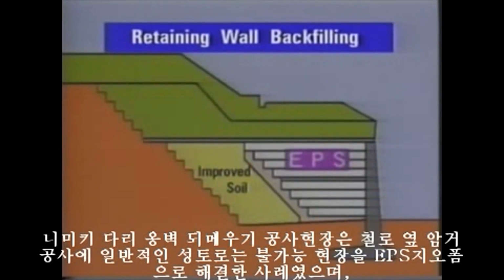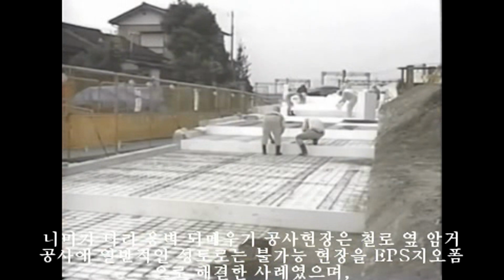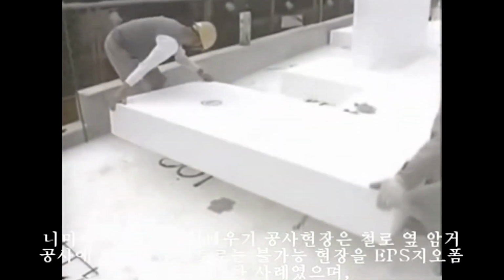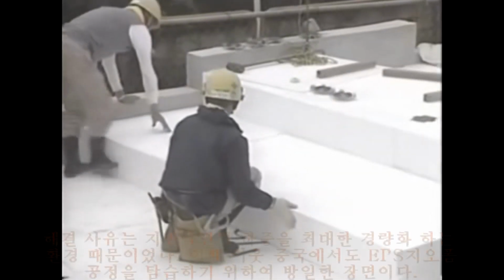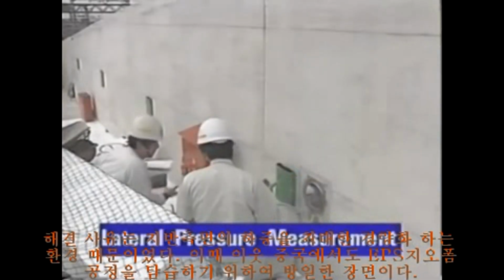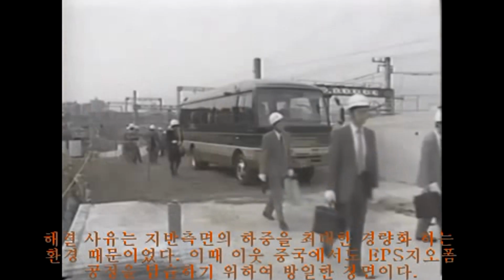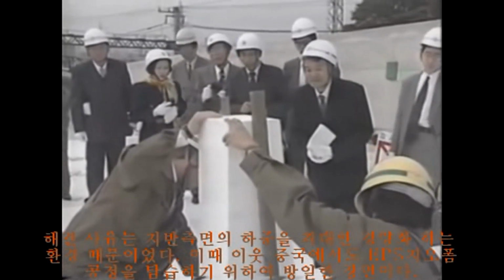At this construction site, where a retaining wall for the Namiki Bridge is positioned between an existing culvert and rail track, there was a concern that the load between the wall and the culvert would be too great using conventional fill techniques. The EPS construction method was utilized to reduce the load on both areas. There have been many inquiries from abroad about the EPS construction method, and study groups like this one from China are visiting Japan, learning about Geofoam construction technology.